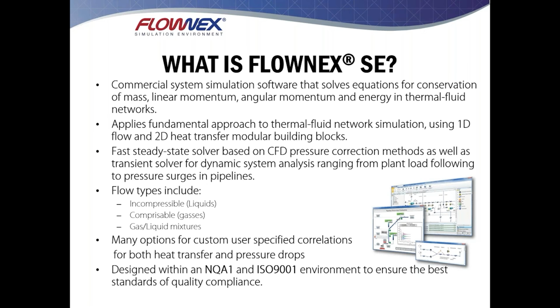We have many different fluid types inside of the software. Obviously incompressible and compressible fluids. For all our secondary flow system modeling components, we have full compressible theory applied, so no incompressible assumptions in those components. And we also have a lot of other fluids available. These can be mixtures of gases and liquids, perhaps oil and air in a lubrication system, or a two-phase fluid like water where you have condensation and evaporation.